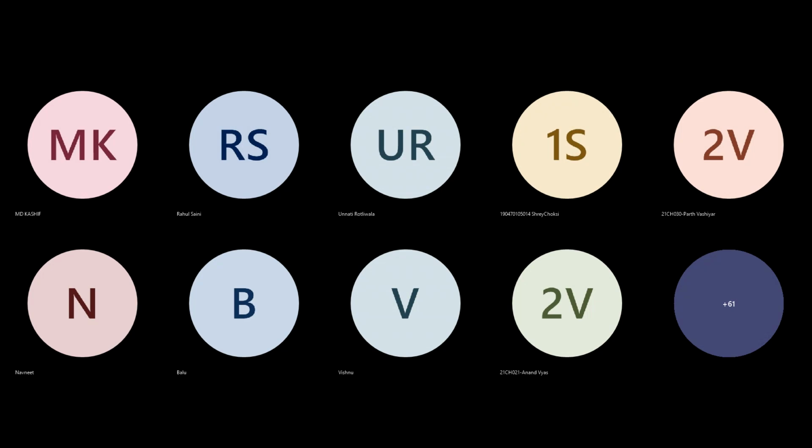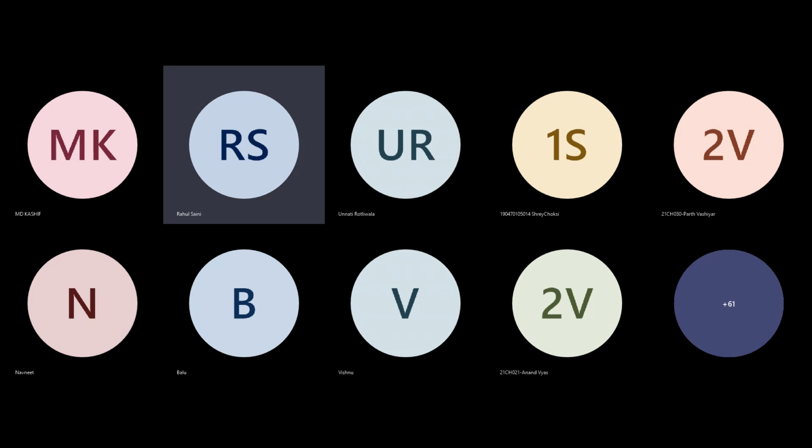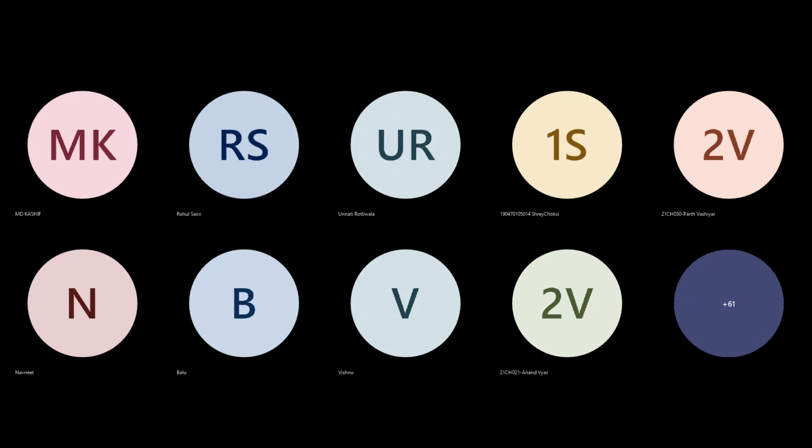But that difference will be very insignificant. So which is the better way to calculate the friction factor, sir, via Fanning or via Moody? If you are doing the calculation manually, then Moody's chart is better. And if you have an Excel sheet, then put the Fanning friction factor formula in the Excel sheet, and that will be better. I would recommend Fanning is the better one.